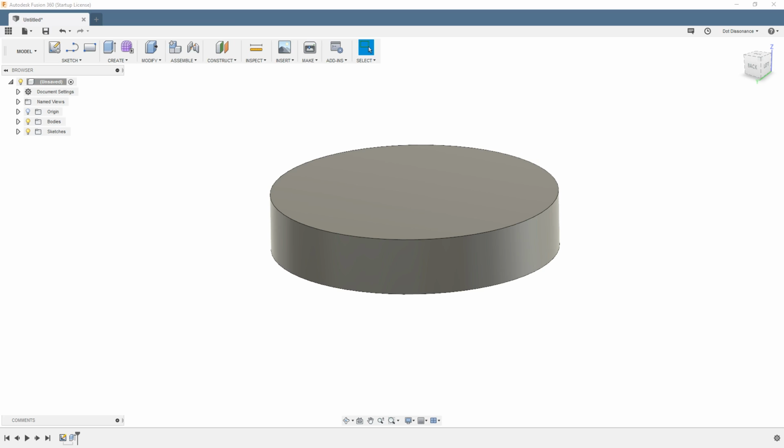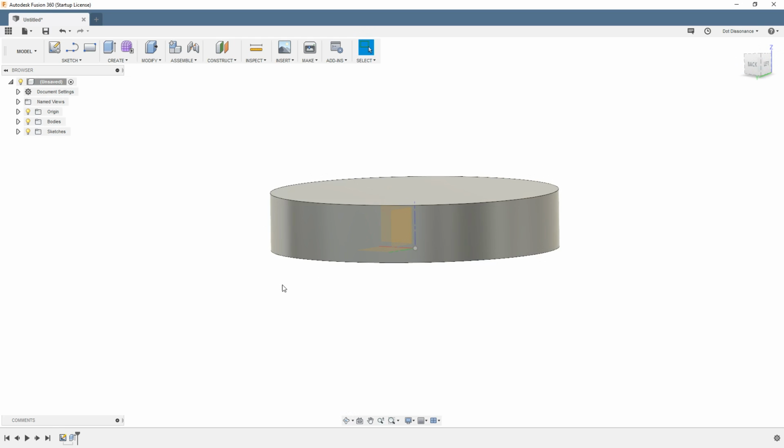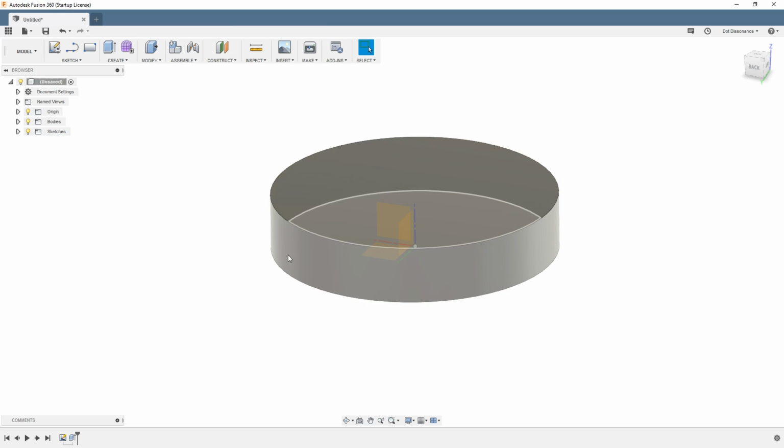So now we have a part like this. It gives us a few more options. So again, to make a sketch, we need to have a plane, like we saw before, or what they call a planar face, a face that is flat like a plane. Not a face that's kind of flat. It has to be mathematically flat, perfect. So I cannot pick this curved edge side of the cylinder right here to put a sketch onto. There's other tricks to get things onto that, but I cannot click it and expect to get into a 2D plane and draw something on it.